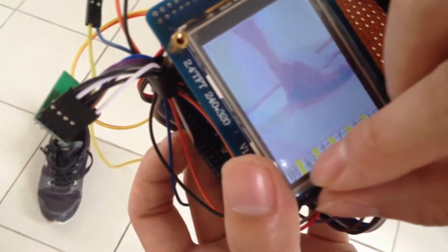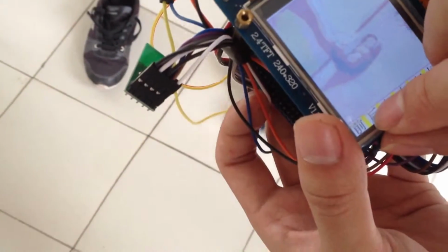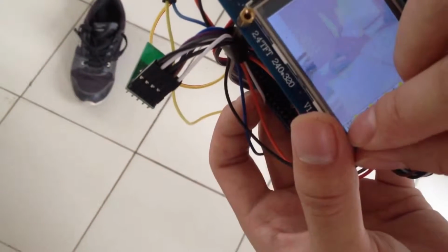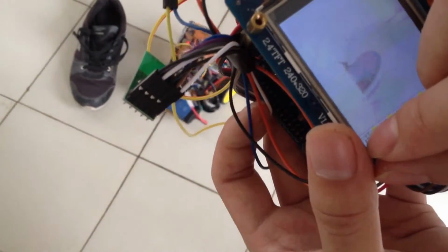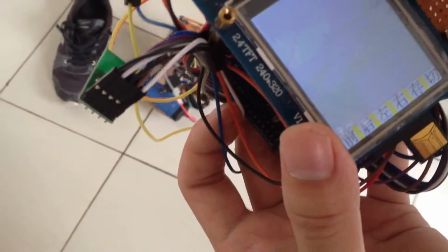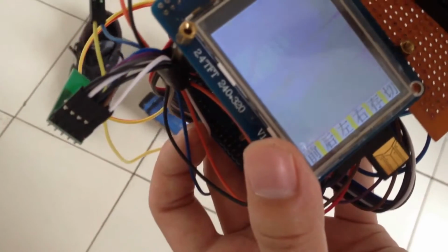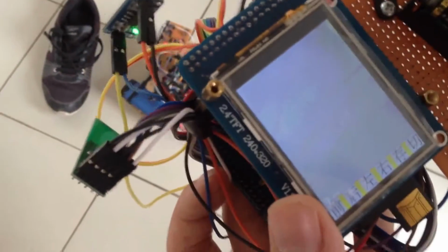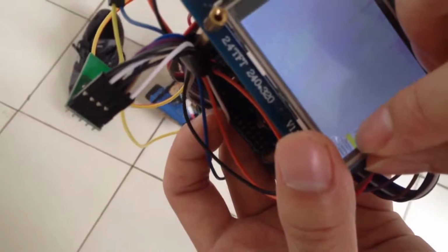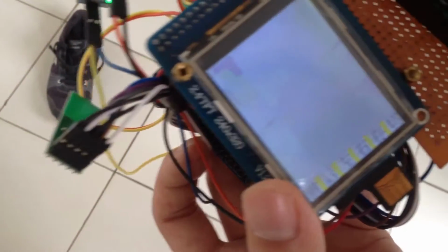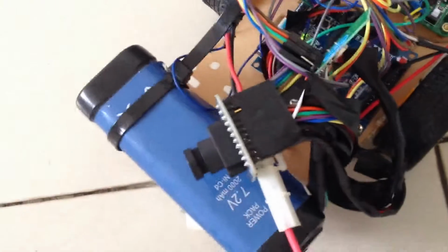And about the data transmission in this project, only the function of the wireless chip is not enough because some pictures will lose data. So I added different kinds of acknowledgement flags and rules to build correct communication between the sender and receiver. I also designed the algorithm so that the car can send a video and receive commands to move at the same time, using only a half duplex wireless chip.